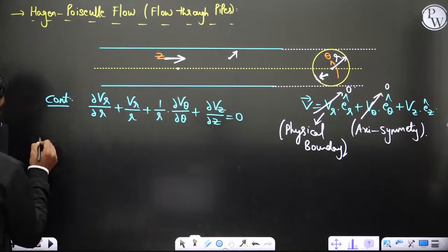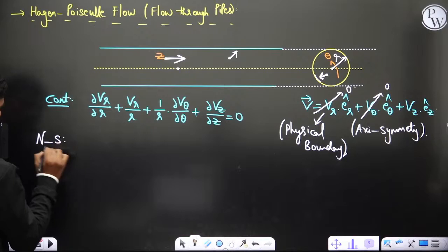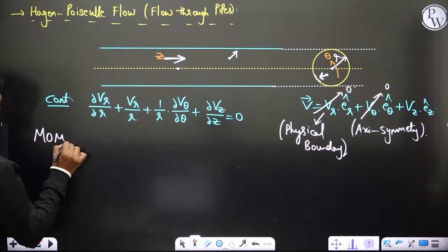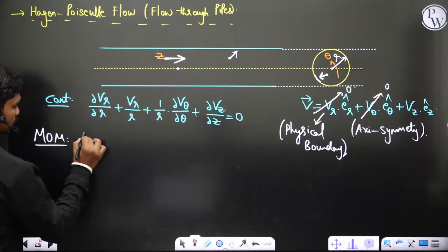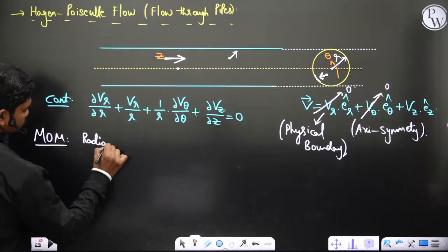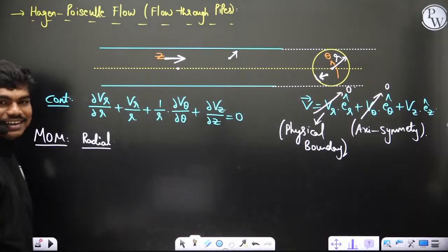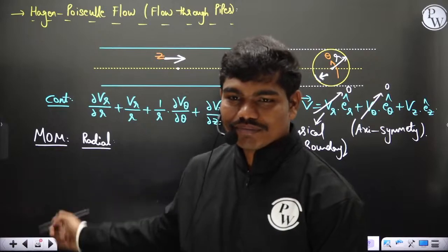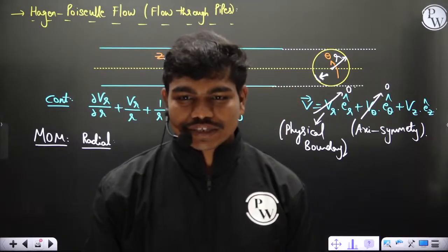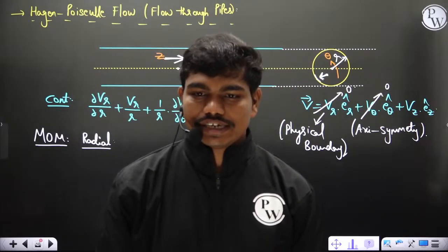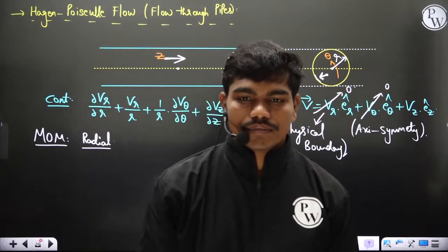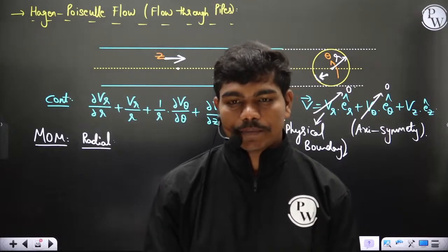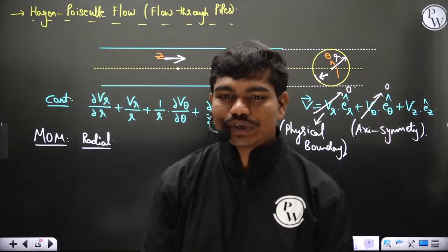Now if you apply the momentum equation, which is basically the Navier-Stokes equation in this case, in the radial direction and theta direction. So radial, if you see, do you want to see the equation? Has anyone seen the Navier-Stokes equation in polar coordinates? Only due to pressure gradient in the z direction, nullified in the radial direction. Yes, because the pressure will try to push the flow only in the forward direction, right? Did anyone of you see Navier-Stokes in polar coordinates anytime?